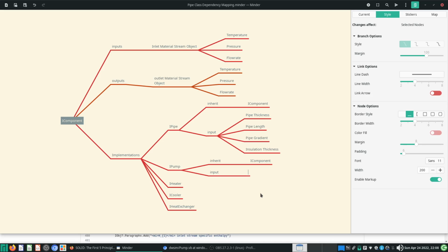Alright, okay, so this is a bit tricky. There's a way you can just give it all the input data. For example, the inlet material stream, you can give it all the data, and then your output will be this outlet material stream. Then of course you can input something like increase in head or NPSH, net positive suction head. So these depend on the way you want to operate the pump. You can actually change your inputs.